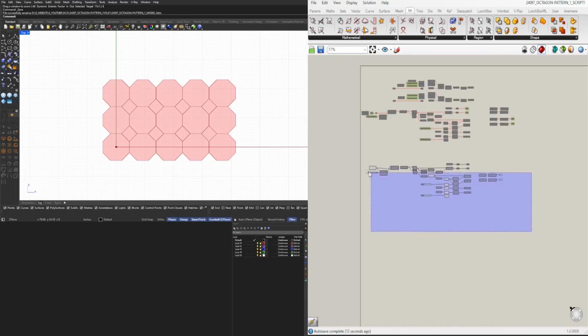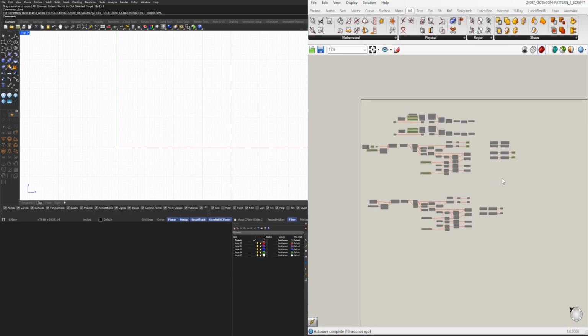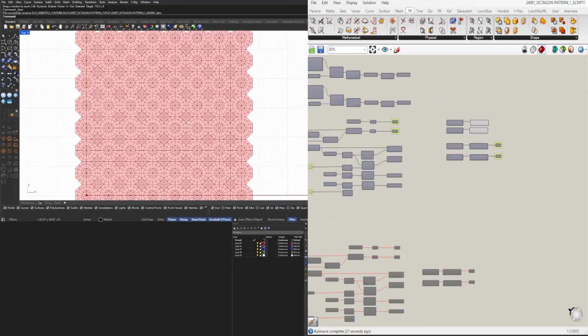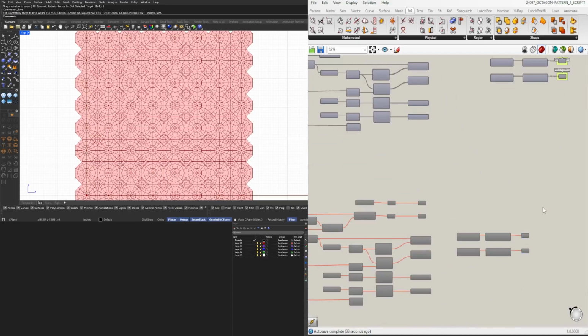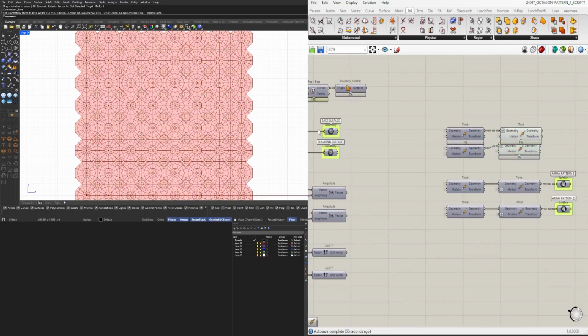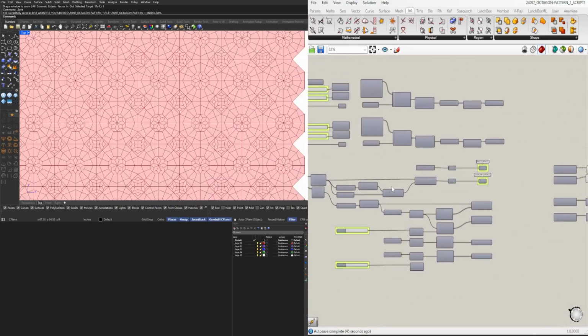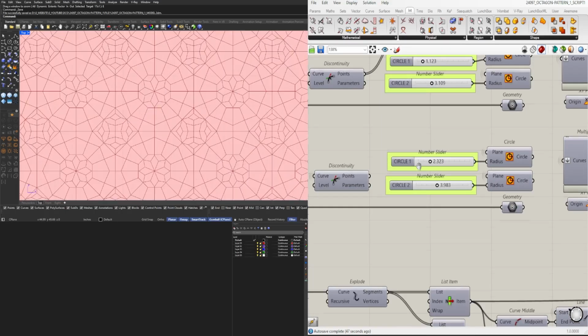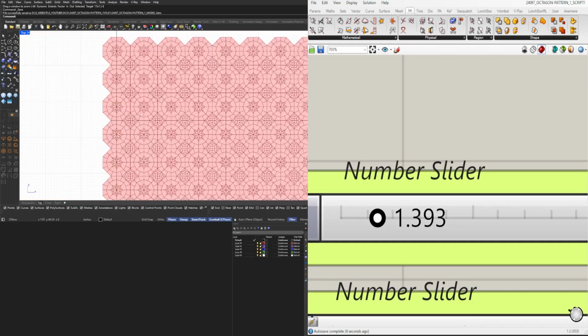From there, I'll disable the script here, and I'll be sharing this with you guys as well, but let me bring this back and show you that this is how complex a pattern can get. And all we did was take these original surfaces and then change them using a technique where we're creating a set of points, subdividing them evenly, and then creating the array once again. What you'll see here is that we can change the size of this, and the pattern would change as well.